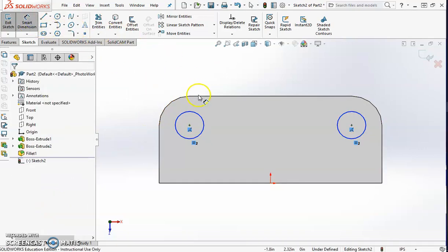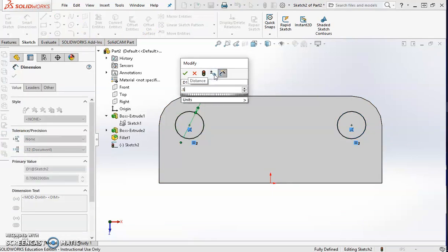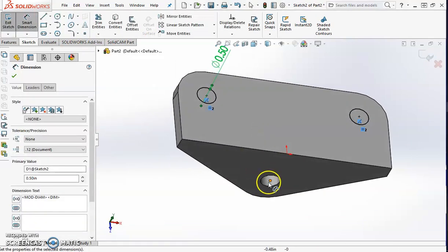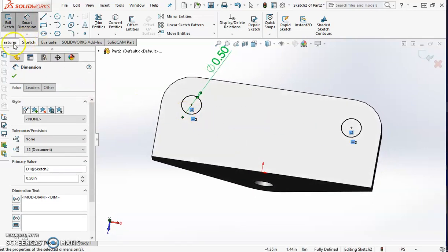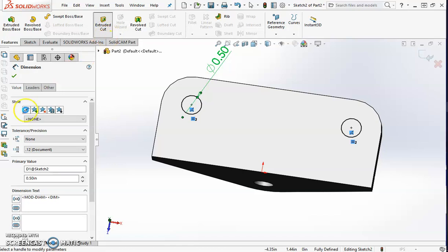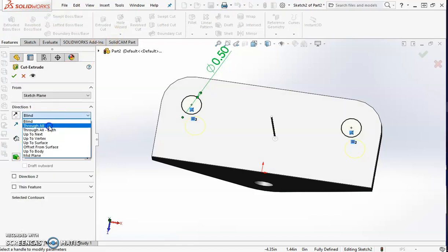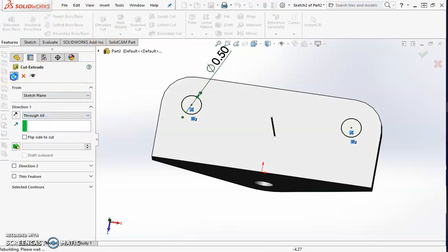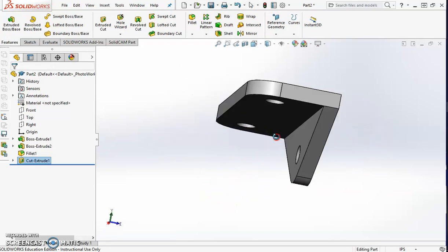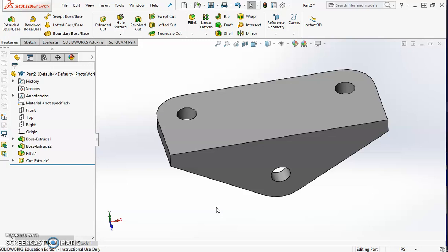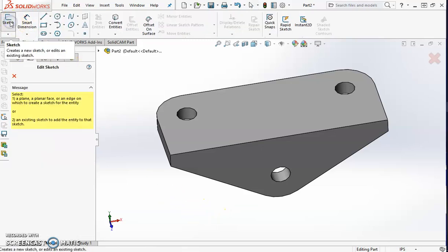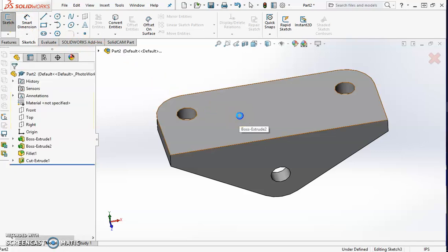And they are also 0.5. And I know that because that little hole that was on the front, meaning this one, it actually says in the picture that there's 3 of them. So these are the other 2. So Features tab, Extrude Cut, and we're going to set this to Through All. Green check. So I would recommend saving right here because the next part is where you're going to be making the plane, and some computers don't like that.